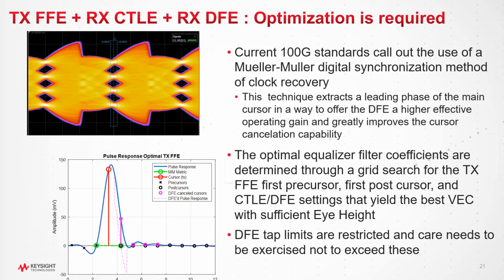Looking at the final configuration and the pulse response is informative. As you can see, in this case, no amount of CTLE alone could achieve a passing VEC. The biggest issue is the lack of pre-emphasis on the leading edge of the pulse response.